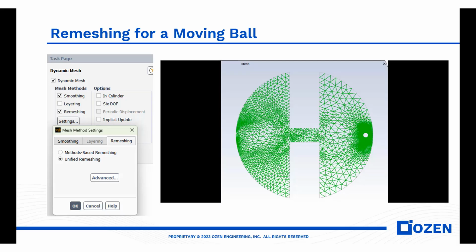Don't forget that initialization does not return the deformed mesh to the original shape. You need to exit Fluent, relaunch Fluent, and reread the mesh in initial form, initial shape, and then by initialization you can start the simulation. But again, by previewing the mesh, be sure that the mesh is correctly set up for dynamic mesh motion.